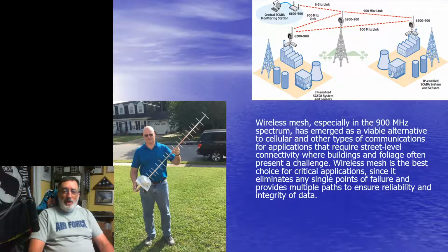We were experiencing trouble burning through the green attenuation, or trees, surrounding some of our sites. So we purchased a pair of these 900 megahertz systems and achieved much improved results. Currently, the first pair of these connects City Hall to Phoenix School. We'll discuss more about what's at Phoenix School later.